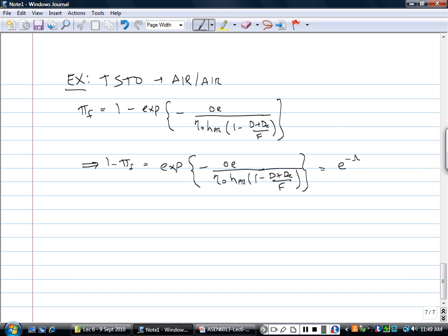Okay, so we'll do a substitution just to get rid of all this nonsense called minus big lambda. The big piece in the bracket is the minus lambda. Make our lives easy. The gamma function we just derived we already know is gamma equals gamma 1 times gamma 2. We're just going to expand that same definition we had, 1 minus pi E1 minus pi F1, 1 minus pi E2 minus pi F2. Now you see why we wrote it in terms of 1 minus pi F. We can substitute it into the gamma equation. We have a 1 minus pi F, which will leave us an empty mass fraction on the bottom along with the lambda term. So we put this together.